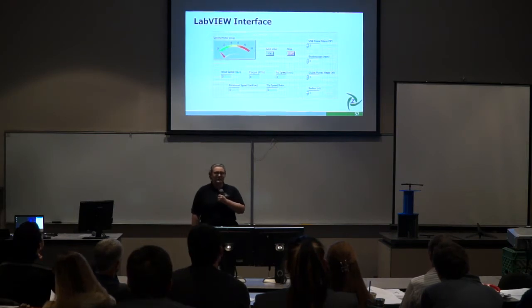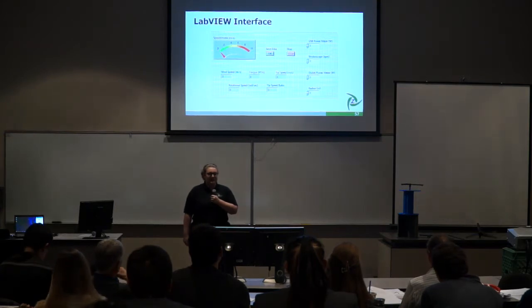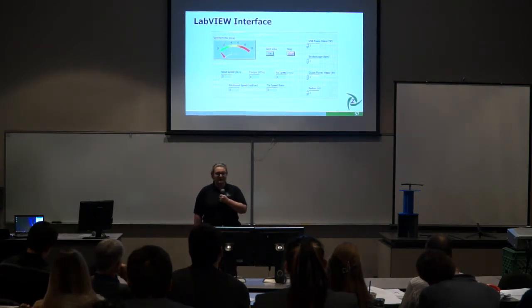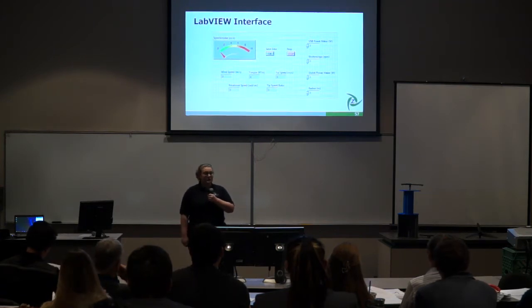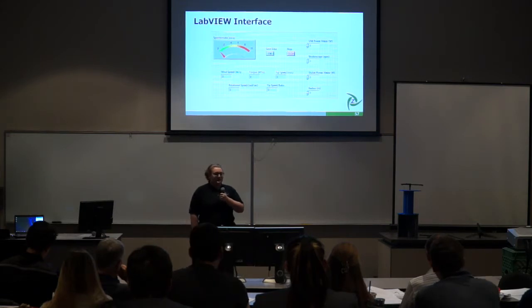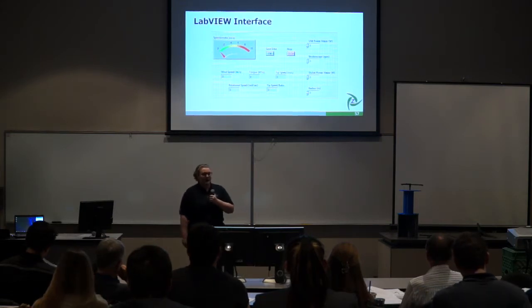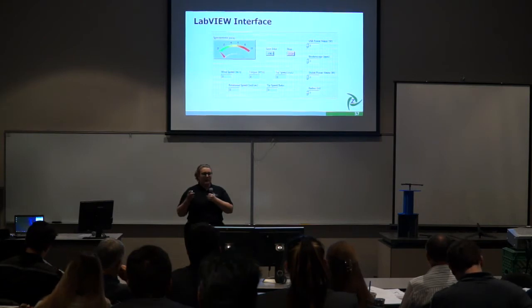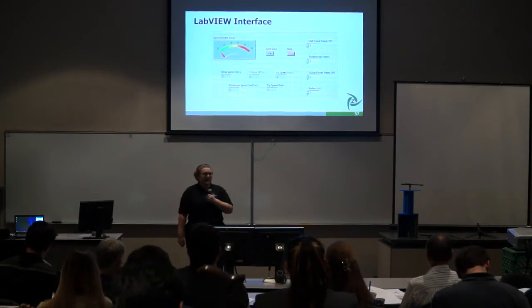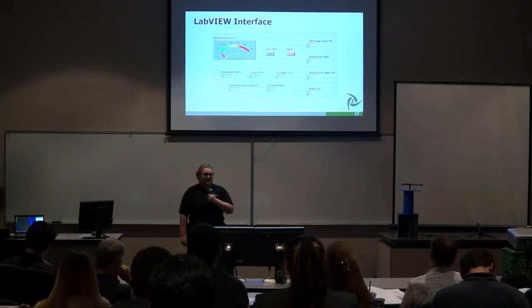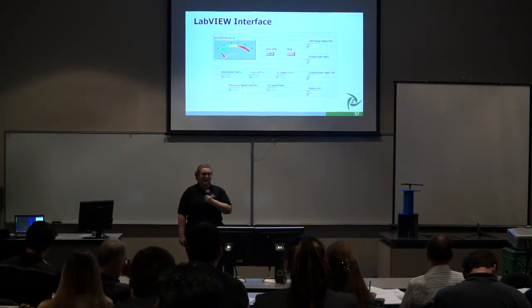On the bottom of the figure are 5 information blocks that we will be seeing: the wind input speed in meters per second, the torque in Newton meters, the tip speed in meters per second, the rotational speed in radians per second, and the tip speed ratio. Additionally, there are 2 buttons that Project Zephyr will be using. The Save Data button allows for the data to be written at that instant onto the Excel file, and the Stop button allows Project Zephyr to stop collecting data from the anemometer at any moment.